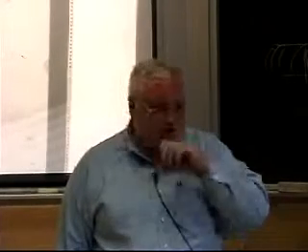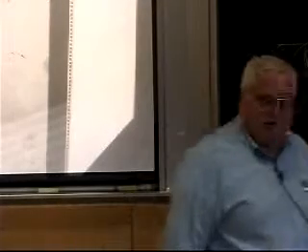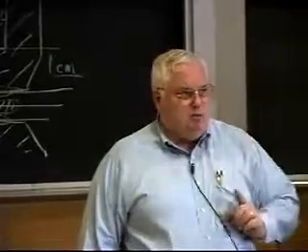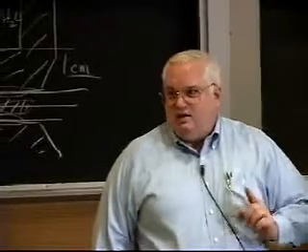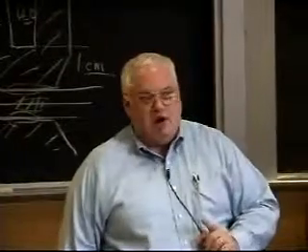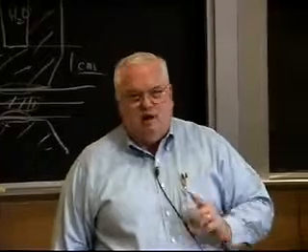Now, if I need to be within a factor of 2, you can't use the Fourier number. You have to solve Fourier's second law, and that's when you give it to a graduate student and say, go solve this in the computer. And you can do that. There are plenty of people who do it. Now we have canned programs that can do this. But the thing is, can you solve the problem in your head and get the correct answer? And 95% of the time, you can do the simple Fourier number in your head and impress your friends.